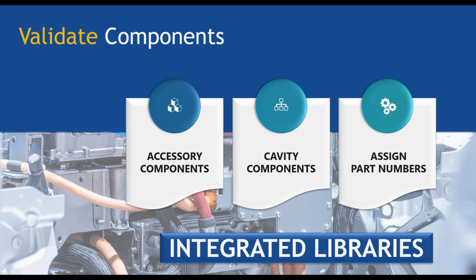We can speed up the design process by allowing Capital to automatically assign part numbers to the design components. In the connectivity data spreadsheet, instead of dictating the wire part number, simply add the material spec, gauge, and color. Once imported, the system will match the spec to the library and add the part number for you. You can also automatically select part numbers for multi-core splices, heat shrink sleeves, spot tape, insulation tubes, etc.